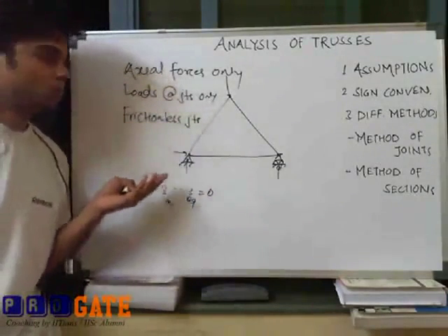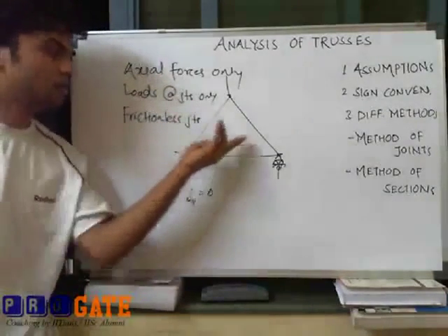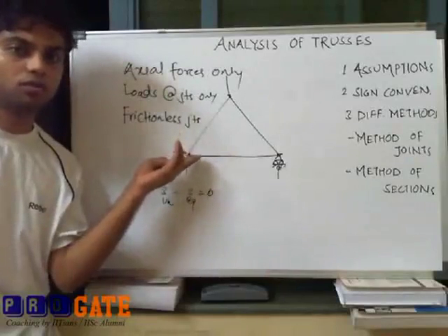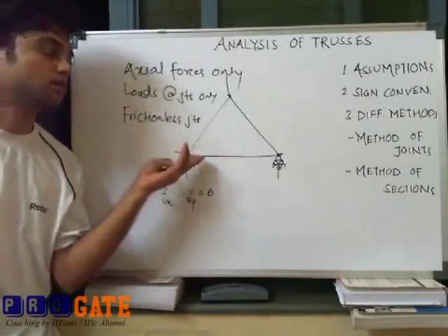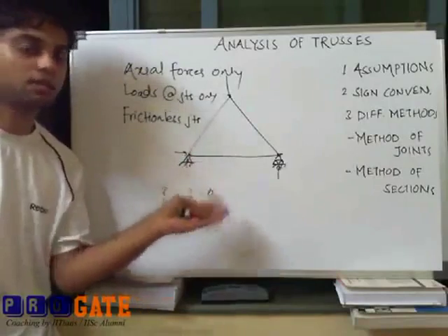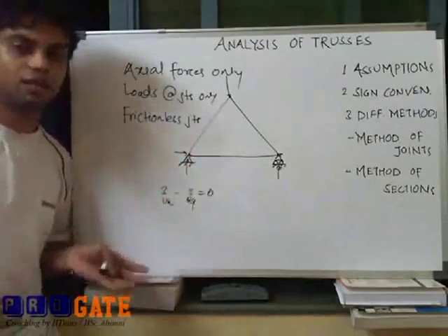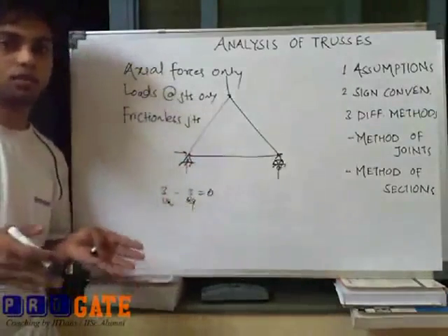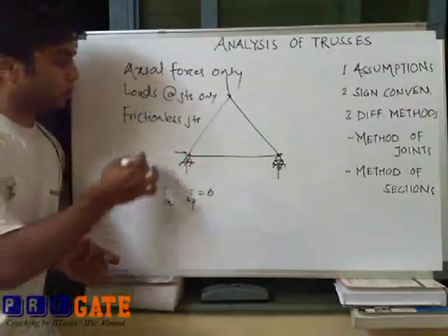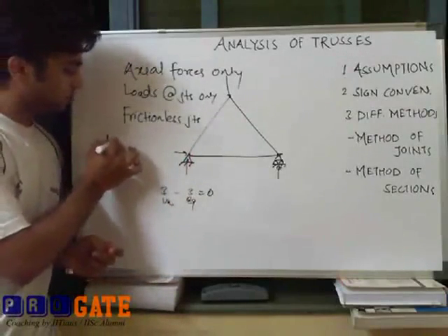Then again, one more assumption we are making, that all these members have some self-weight, but while doing analysis we will neglect the self-weight. Self-weights are negligible as compared with the axial loads that they will be carrying. So negligible self-weight.